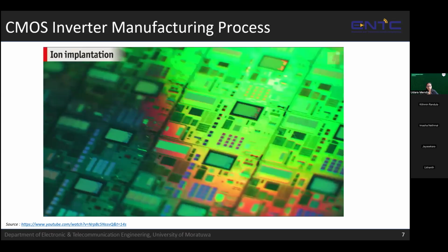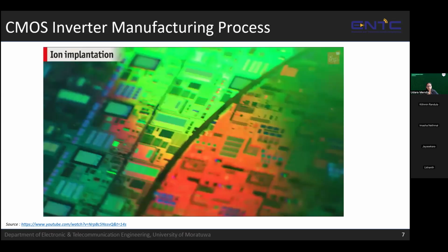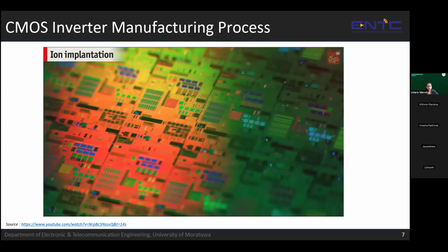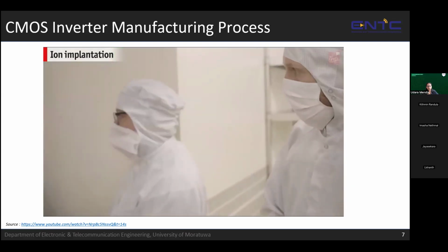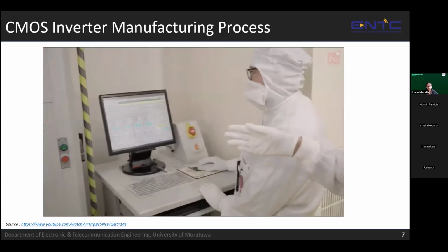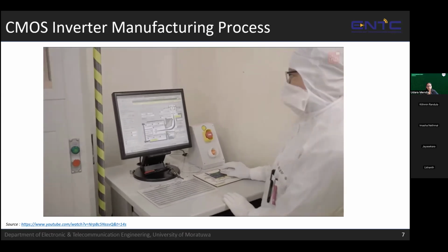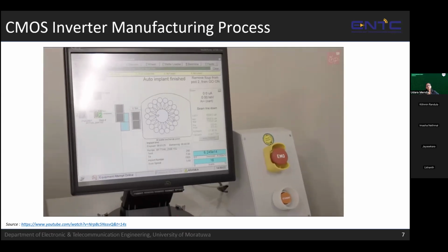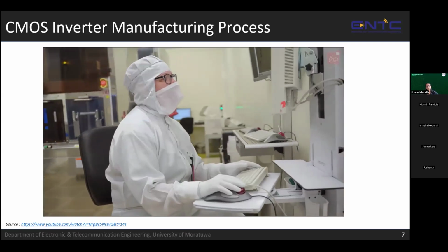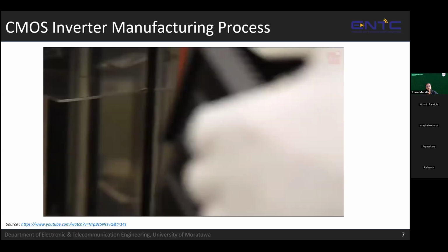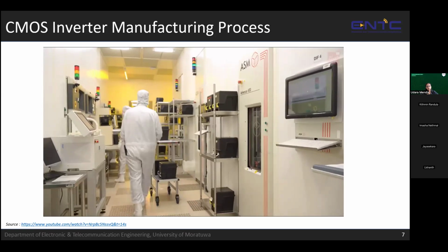To build our active devices and change the connectivity of our silicon in well-defined areas, ion implantation is a very important method. It involves shooting charged atoms into the silicon. We use boron and arsenic ions for implantation, to name but 2. We only need a very small number, like 1 dopant per 100 or 1 dopant per million silicon atoms. It turns the silicon into a p-type or n-type semiconductor.